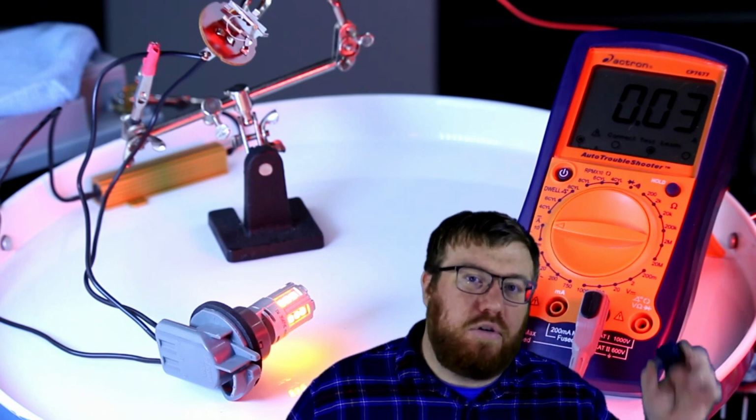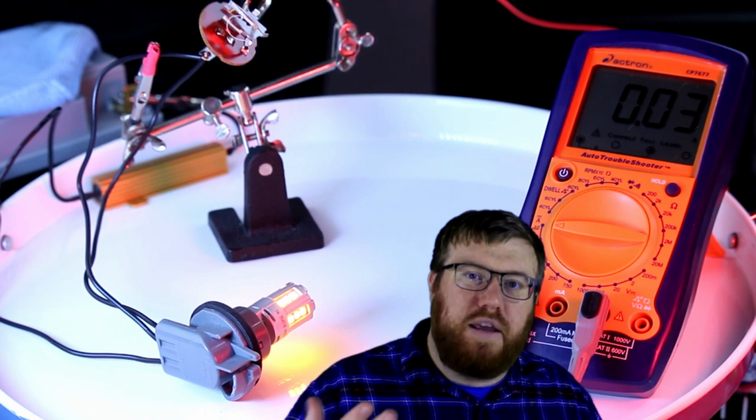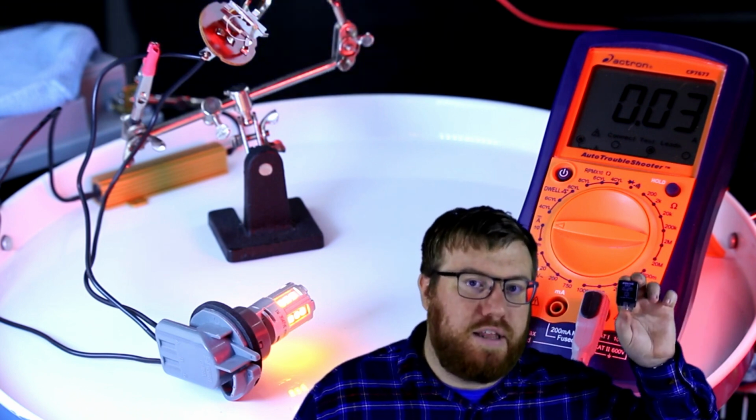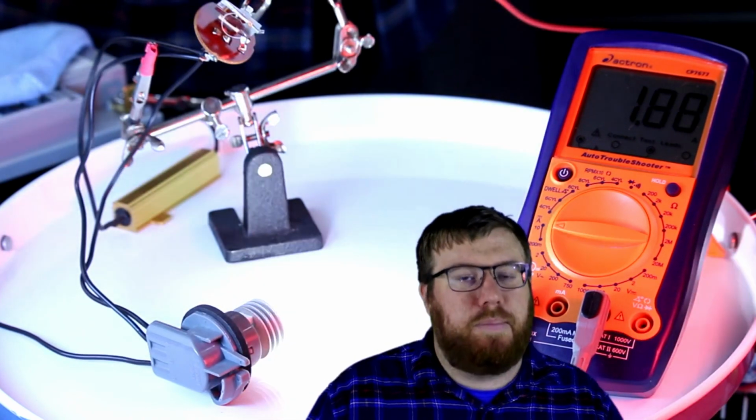Modern flasher units are more digitally controlled and sometimes have artificial sound in them to replicate the original sound of a thermal flasher. Sometimes you don't even get a replaceable unit like this anymore, and it's just a system that's built into an ECU or similar computer. So when you upgrade your turn signal bulbs to LEDs, sometimes it's necessary to get a flasher unit that's compatible with LEDs, or if you have one of those ECU setups controlling the signal, you sometimes have to trick it into thinking that you have normal bulbs when you have your LEDs installed. This is a resistor unit that will be installed parallel to the bulb.